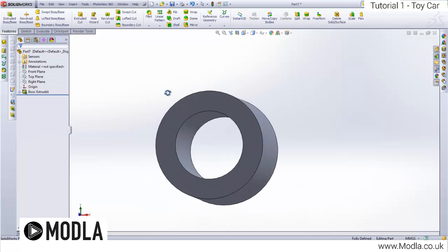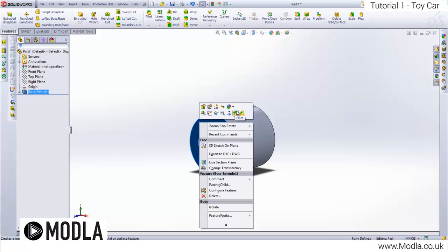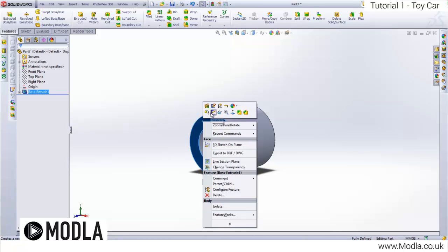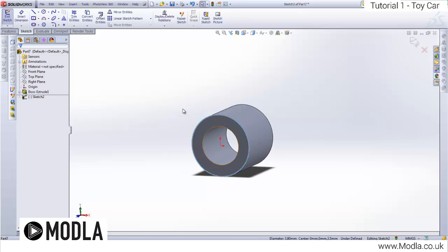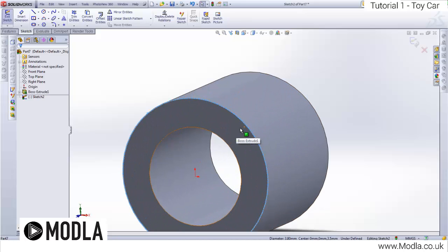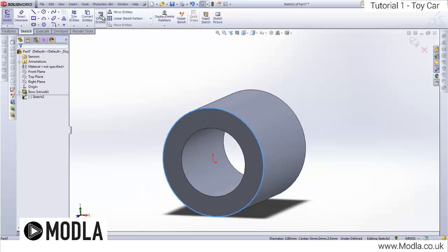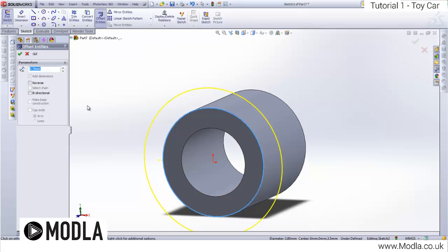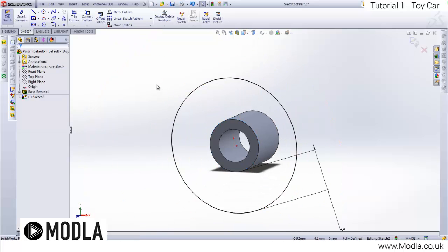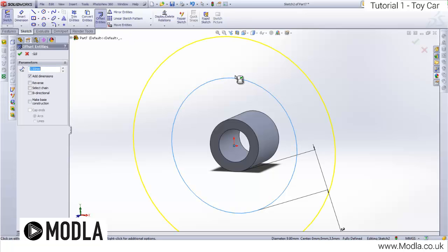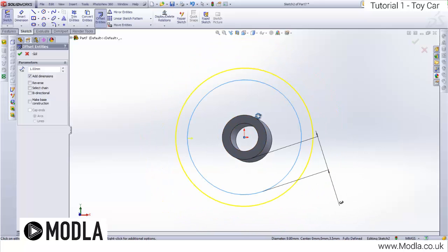Now what I'm ready to do is select on this face here. Okay, I'm going to create offset. What I can do is I can offset now features from the 3D model. So if I'm in a sketch, and I go offset there, I'll offset that face just by selecting that line by 3 mil, and I'm going to green tick that, okay? And then I'm going to offset this, okay, by 1 millimeter.